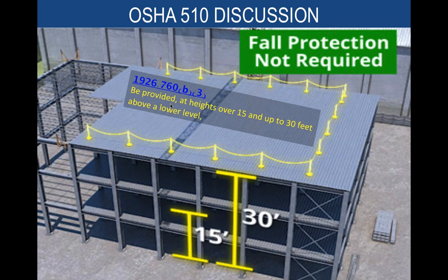If you have to lift your legs to get underneath a scaffold, you're not supposed to be under there. Okay, it's going to have to be open access to be able to easily traffic through, and it's going to have to be decked from on top and toe guards in order to protect us down below. Okay, and then we're still going to be in a hard hat zone.